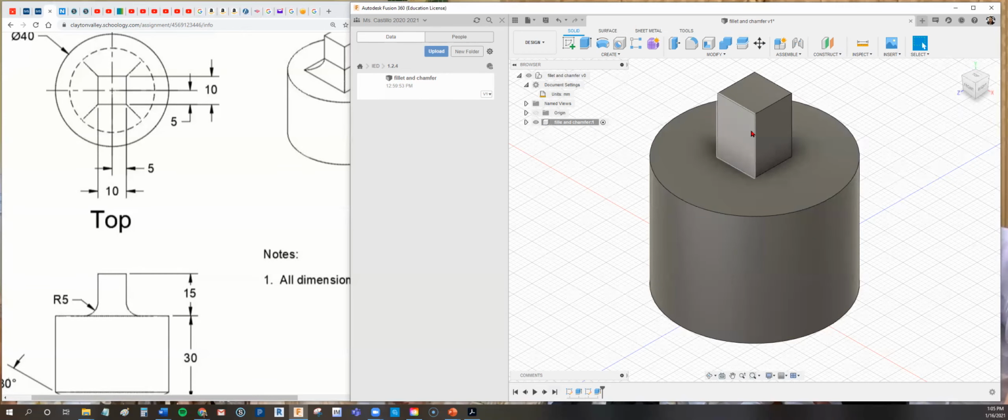and then on top of it, we extruded and created this rectangle box. Okay, so now for this box on top, we're going to go ahead and fillet the edges. Now I know in Mr. Hughes' video, Mr. McAllister's video, he explained something different. I'm just going to go ahead and, without confusing you, do it this way. Okay, so now we have the cylinder, we have the box on top.